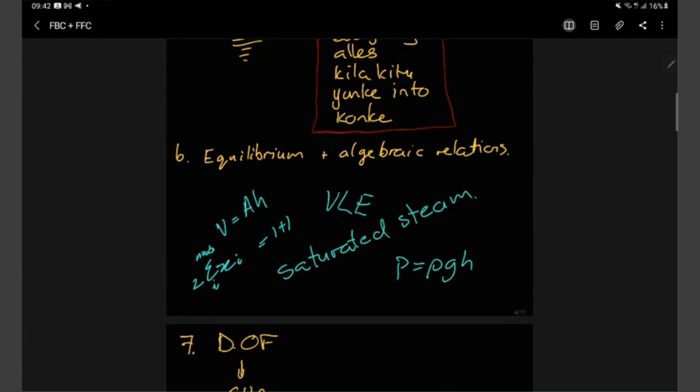So be careful about that, because this is a point that a lot of people make a mistake when they are developing models and neglect to consider the fact that a saturated stream needs only one specified either temperature or pressure to fully define that stream. But yeah, that equation, sum of xi, that makes no sense. It's correct if x is something that actually ends up being 1, but yeah, couldn't think of a good expression for x. That's just there to confuse you.